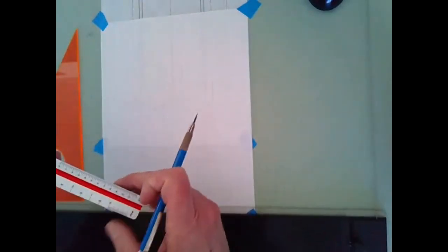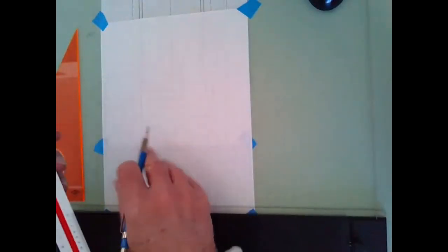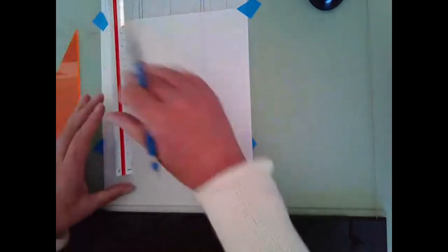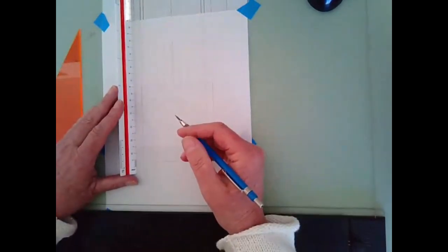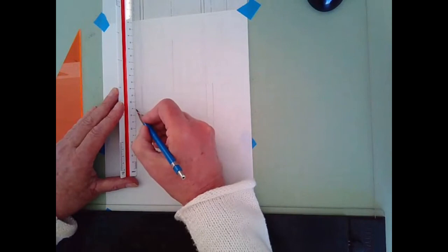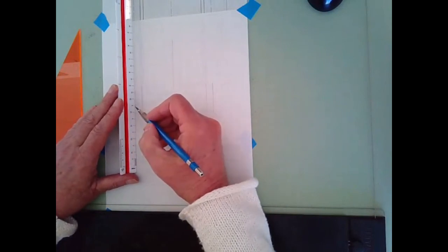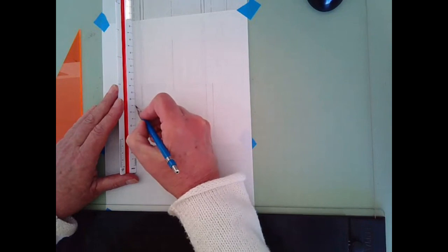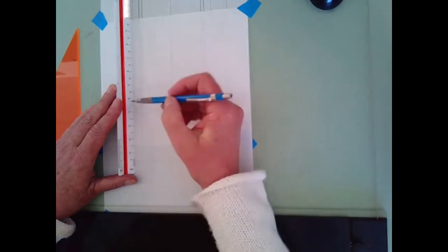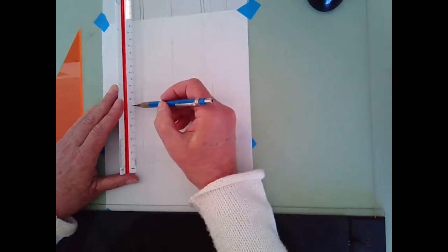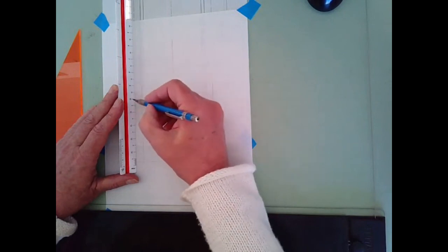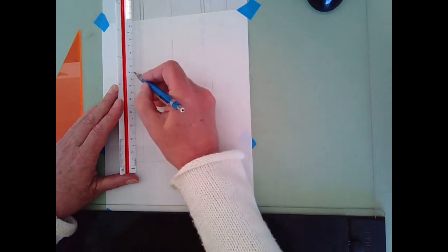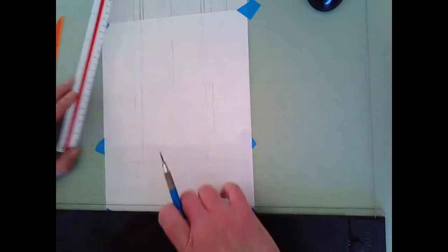So I know that I've got to be 8'6", and I have to be at 3/8 inch scale, because when I'm using a floor plan, I can't change my scale for the elevation. So I'm going to be at 3/8 inch scale, and I'm going to come up 8 feet to the bottom of the fascia, and then I'm going to move it up 6 inches. And there's 8'6". And then I'm going to go ahead and count my 5 feet. So 8 plus 5 is 13. So 1, 2, 3, 4, 5. That's going to be the tip of my roof.